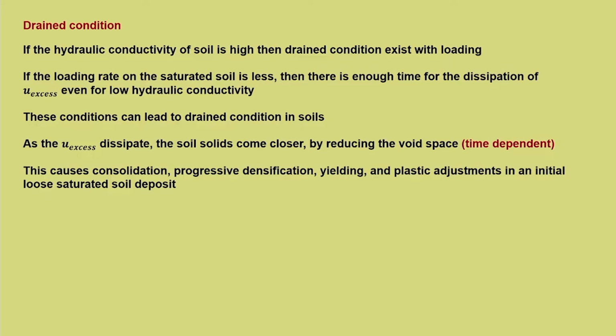So, that is very important. You need to understand that it undergoes consolidation. Consolidation is a process of densification for loose samples, and when it happens, this is an elastoplastic response. There will be a kind of yielding that will happen to the soil and plastic adjustment of particles.